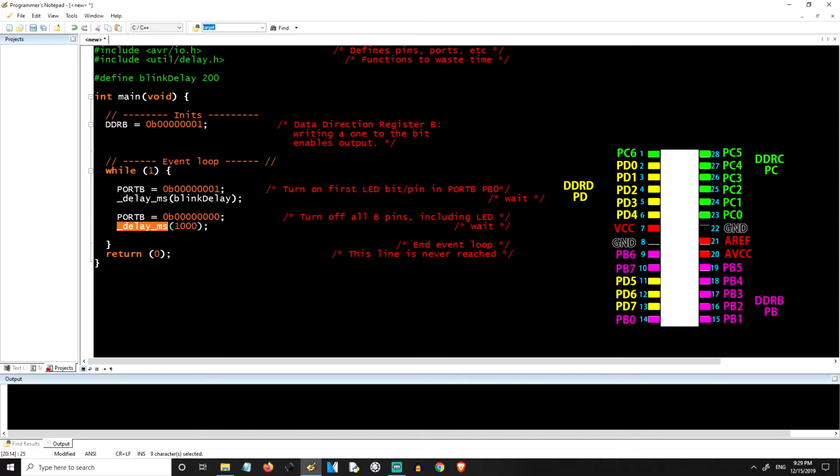All right, and then we have another delay. So we turned it on, we waited 200 milliseconds, we turned it off, and then we have a long delay of 1000. You could do something like blink delay plus whatever, 1000 or whatever you want. Let's just say 1000 just for simplicity right now. And we'll take a look at how that looks. And we have the semicolon to close that out.